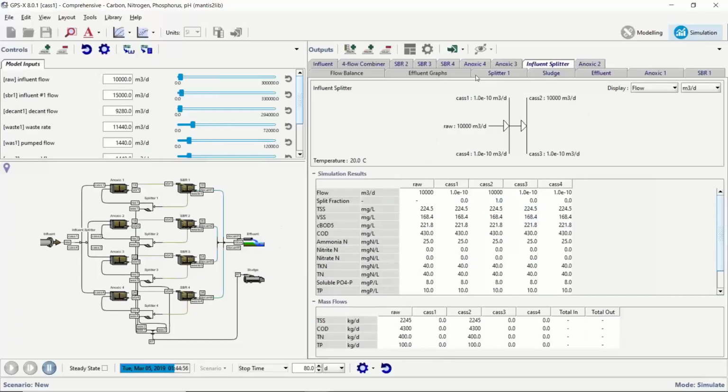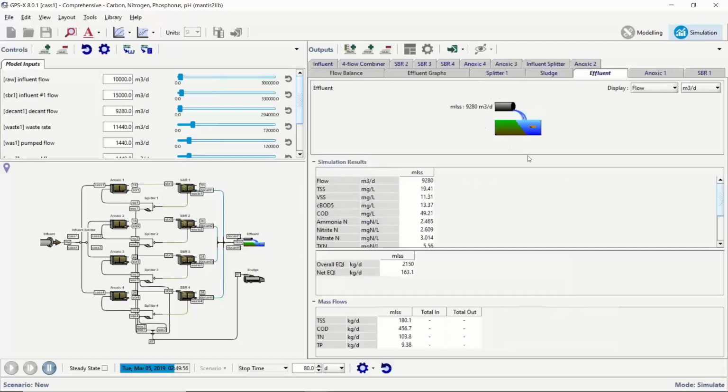All right, so in this case, we're actually doing extremely well. We're not nitrifying quite as much, but our effluent nitrate is like 3. We've got all that anoxic zone and anoxic time in the reactor as well. We're denitrifying quite a bit, I think.